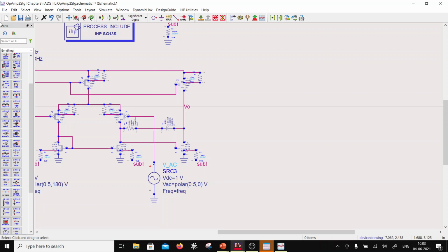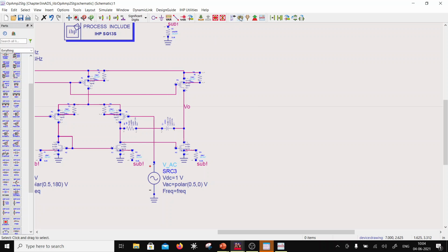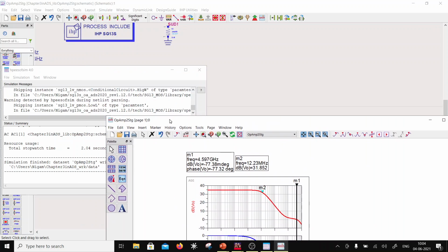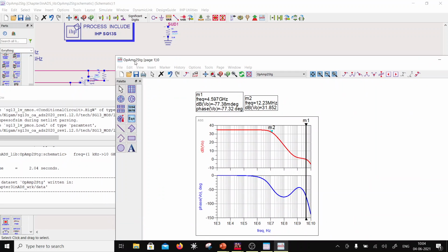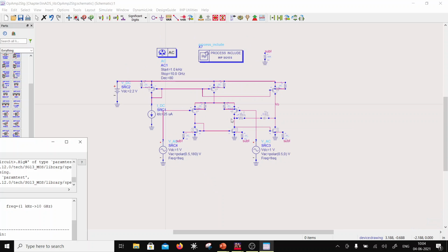And I'm going to resimulate to see if it looks okay. So I'm going to save it to simulate it. Okay, so this almost is the same performance, isn't it? Okay, so I have the op amp. So what I want to do is I can do some diagnostic on this op amp. Okay, so this is a linear simulation or AC simulation here, where the components are linearized, supply restrictions are not there.